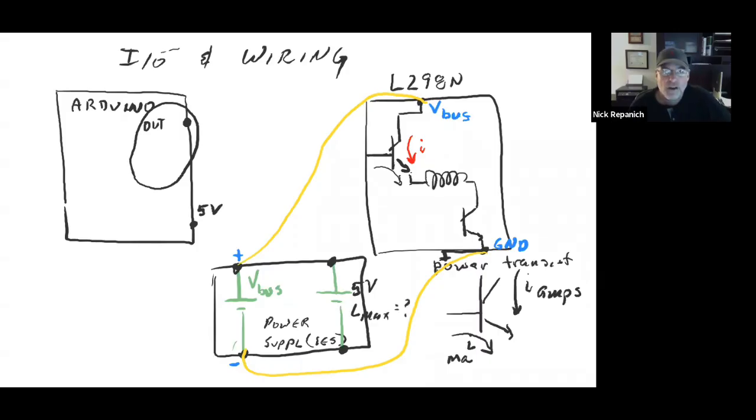First thing you want to know: oh, it's an output. How much can I use? Oh, it's only 200 milliamps. Oh, okay. Good. The other thing you kind of want to know is, is it designed for inductive loads or resistive loads?